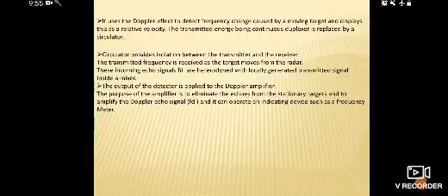So the transmitted frequency is received from a target moving relative to the radar. These incoming echo signals, fd, are heterodyned with the locally generated transmitted signals inside a mixer. The output of the detector is applied to the Doppler amplifier. What is the purpose of the Doppler amplifier?